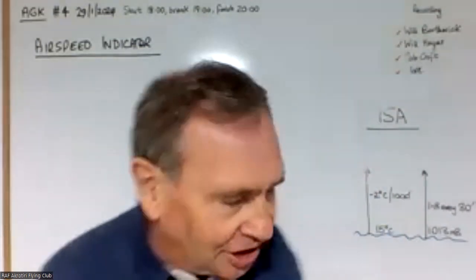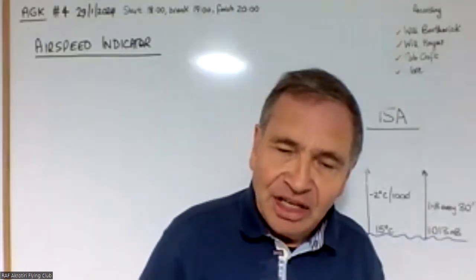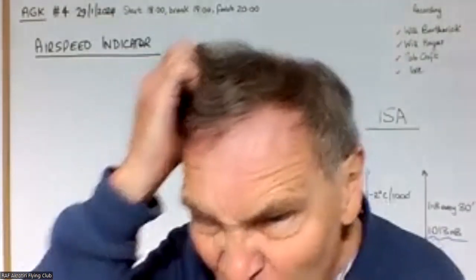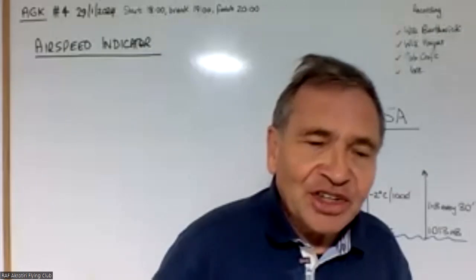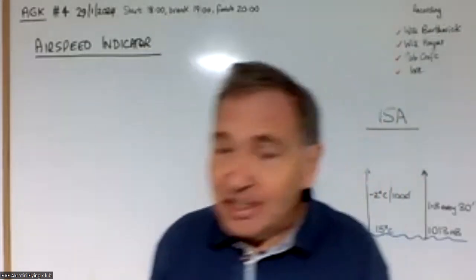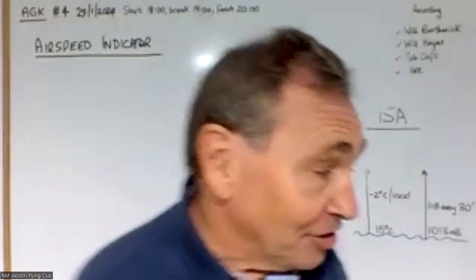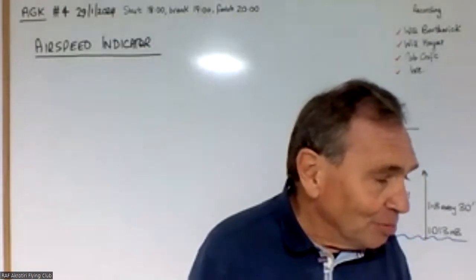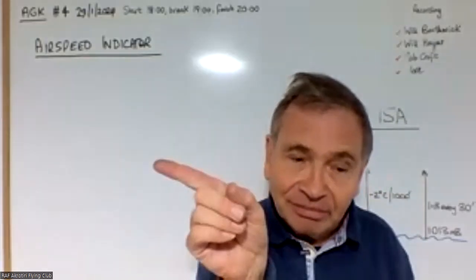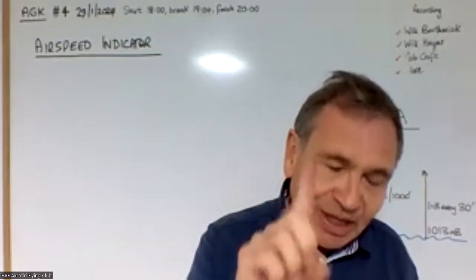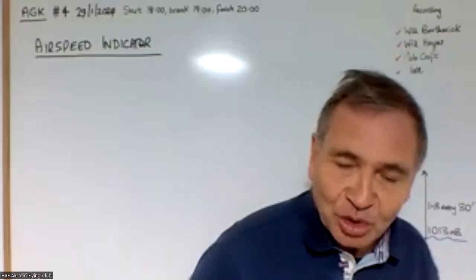So that's a blocked thing on the ground. And in fact, part of your checks, as you apply power on the runway and you get faster and faster and faster down the runway, one of your first calls as a pilot is you look at your airspeed indicator and you shout "airspeed live." And what you mean by that is the needle's moving. That's all you're interested in. Airspeed live means your airspeed indicator is making a reading of some sort.